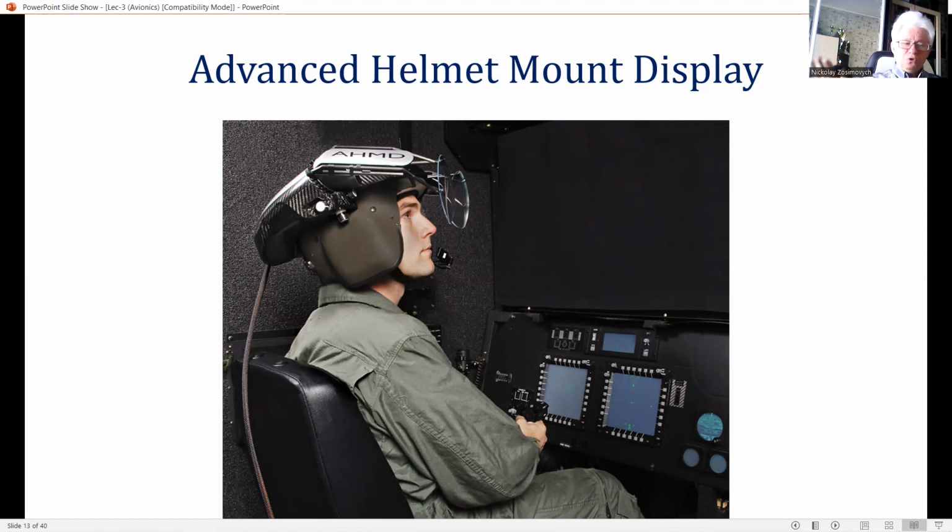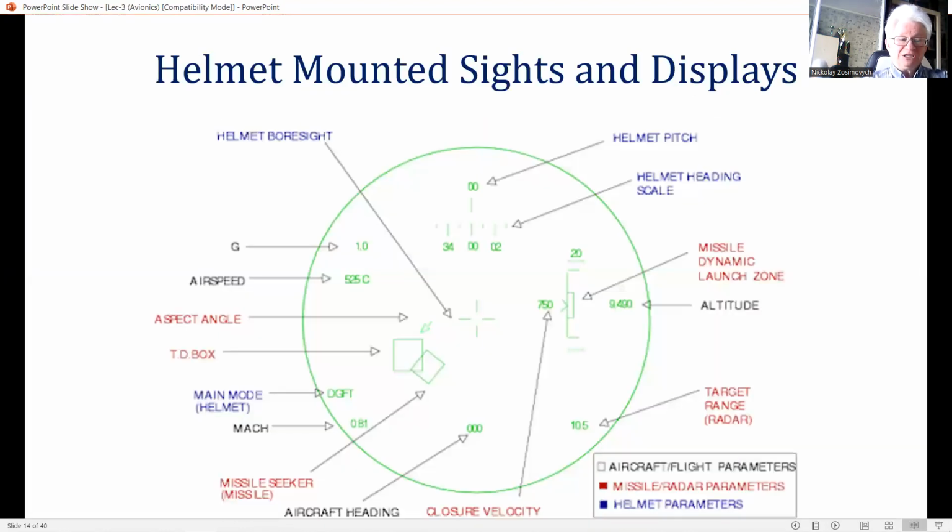The pilot no longer needs to turn the aircraft until the target is within the FOV of the HUD before launching the missile, and this is a very, very positive characteristic. The maximum boresight angle for missile launch using the HUD is less than 15 degrees, even with a wide FOV HUD, compared with about 120 with an HMS and highly agile missiles. This gives a major increase in air combat effectiveness.